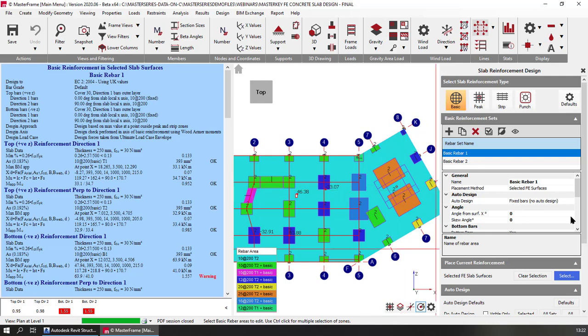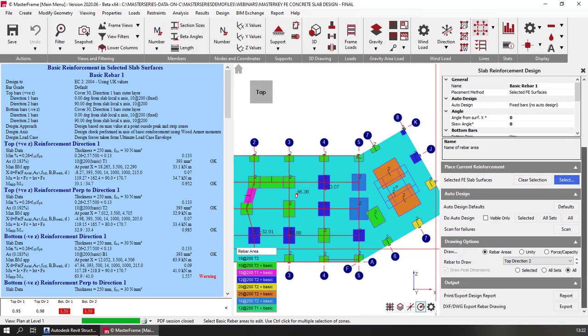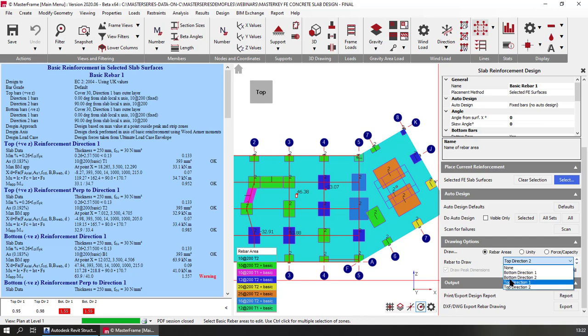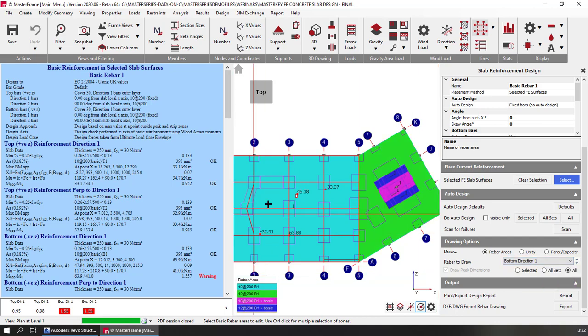We are looking at the moment in our top direction 2. And we can then look at bottom direction 1, and we can see over here the T10 basic is perfectly good, and over here we have got T12 basic plus additional 12s and additional 16s, because we actually have this transfer slab situation where we have this huge big column coming down, a single column which is then carried at the ground the first on 2 separate columns out here and here. So everything is all designed.